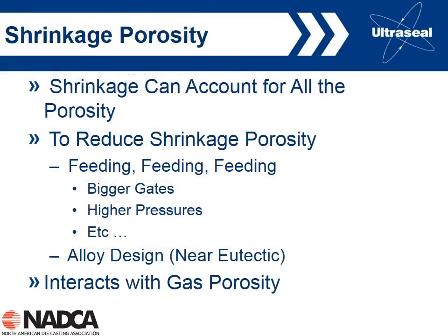So in summary, for shrinkage porosity, we can say that shrinkage can account for all of the porosity that we see, although that's not necessarily where it's coming from. We're going to talk about gas porosity in the next few slides or so. So we're not saying that all porosity comes from shrinkage, but clearly we need to give shrinkage equal weight in our porosity considerations.